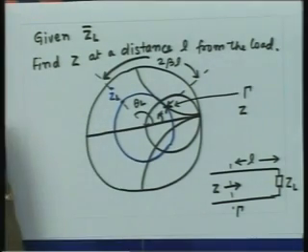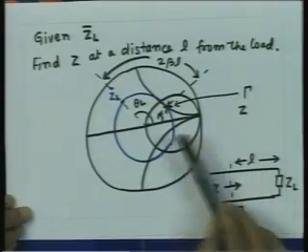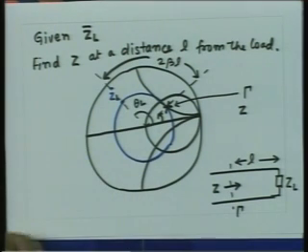So, the transformation of impedance or admittance is exactly identical on the Smith chart. Only, as we saw earlier, if I have to find out the phase of the reflection coefficient, then the marking of the reflection coefficient axis comes into picture, and then you have to remember that for the impedances the real axis is rightwards, whereas for the admittances the real axis is leftward. But otherwise, for transformation calculations, once the impedance and admittance are normalized, the procedure is exactly identical.